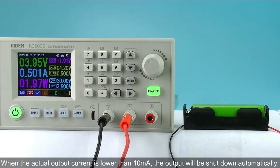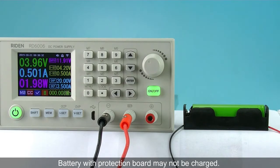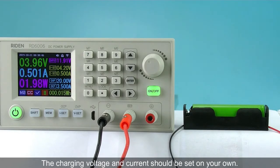When the actual output current is lower than 10 mA, the output will be shut down automatically. Battery with protection board may not be charged. The charging voltage and current should be set on your own.